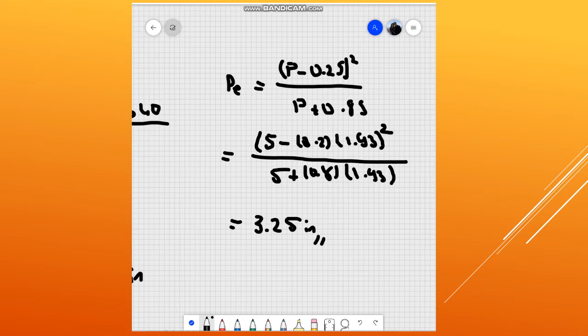That is the excess rainfall, which means that in this area, which is an 83.8 curve number land, you can see there are curbs, parking lots, plazas, and so on. So 18% is paved roads, 30% is residential which is 30% impervious, and there is 12% residential which is 65% impervious. Most of them are impervious.